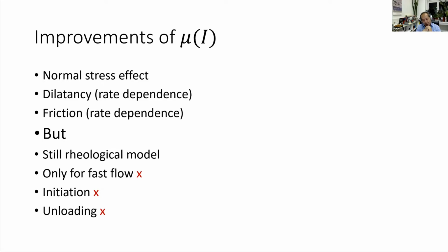But there is a but, and I put it here, there is a big but, right? The big but is that it's still a rheological model. This means it expresses the stress as a function of the strain rate. It is only for fast granular flow, right? And it does not account for the initiation. If you look here, every debris flow starts with a landslide, and that is solid mechanics. This means if the speed is very, very low, close to zero, you cannot use it.